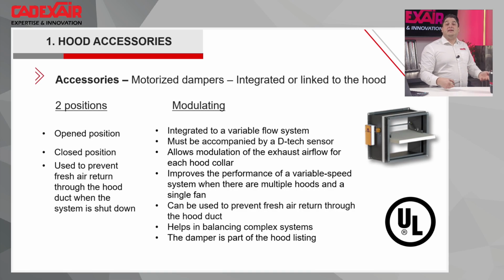So it's something that can be done. It also helps with balancing and everything. Same thing as the two-position damper: we can use it not fully open or fully closed, to help balance. So that's something that can be used to improve your energy efficiency with the modulating damper.